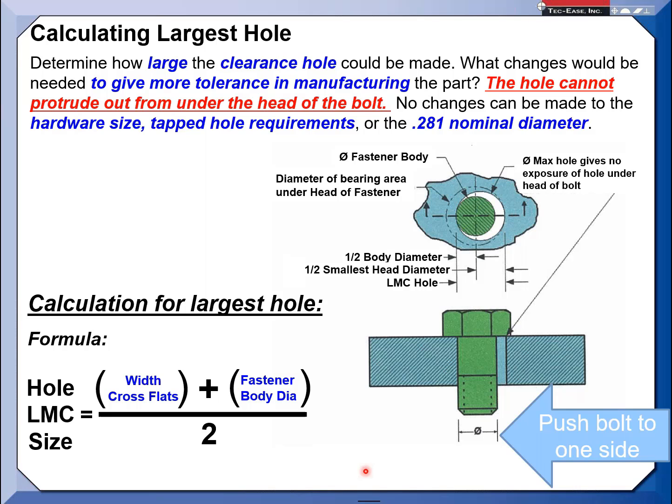And they questioned themselves, how come we're using the drawing block tolerance, plus or minus 5 thousandths, on the holes? And when they looked at all the holes they're putting in that were plus or minus 5, it's like, why are we doing this? We have some parts that are coming in non-compliant. Can we open the tolerance up? And they actually came and presented this to ASME. And they were asking us, hey, can you put this in the book?